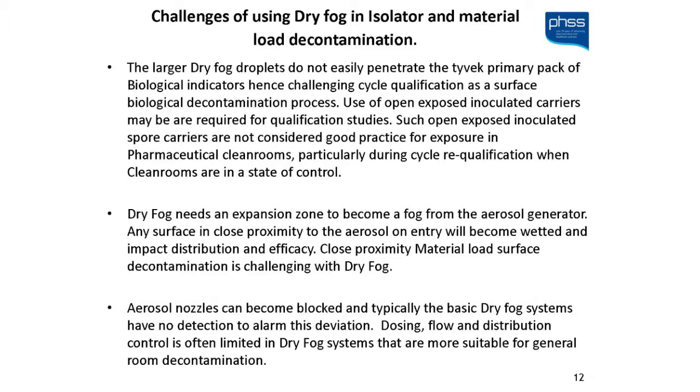So up at 50%, yes, you can still get enough space in the volume to get peroxide and get your 6-log efficacy, even if you're up at 60%. But you're a lot closer to getting condensation visible because you're overloading the cycle, because classically there's enough efficacy just by a few grams in a cubic meter volume to get decontamination. The extra injection is all about gas distribution challenges.